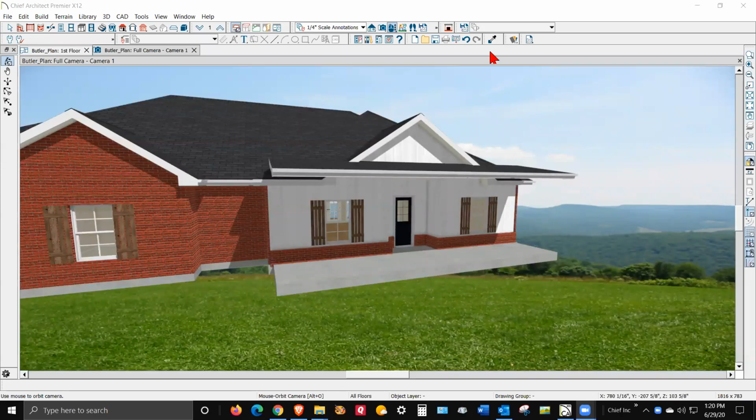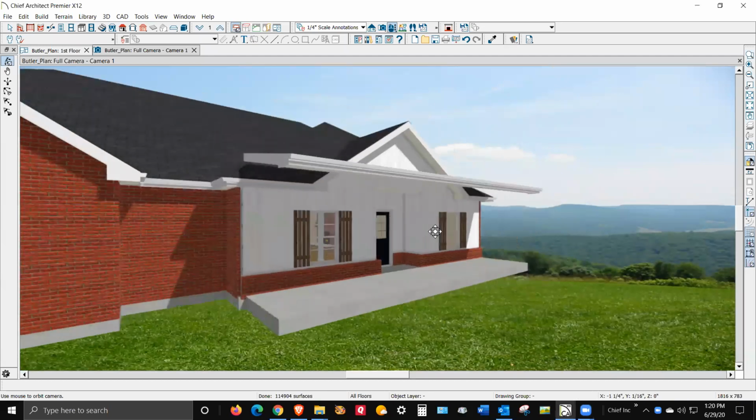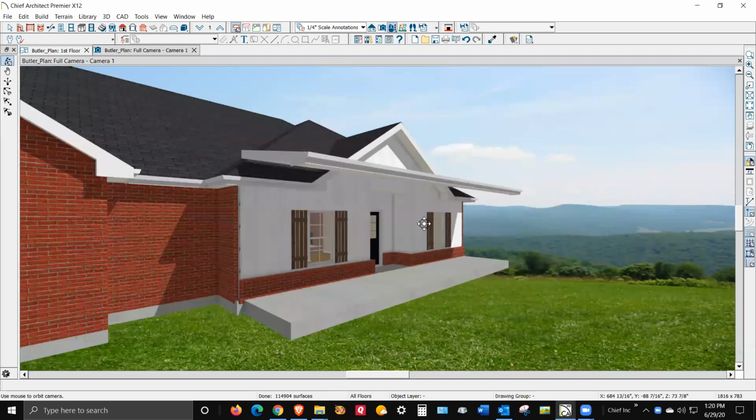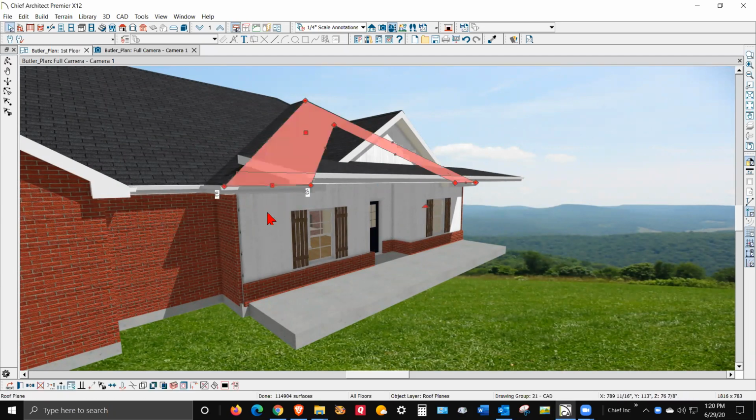I just downloaded and opened your plan. I opened it in X12, and that's not compatible with Home Designer Pro 2018, but the mechanics will be the same. Now, I'm not quite sure from what you said in your post where you want this shed roof, but if there's enough headroom, I would probably want it down here connecting to this roof here.